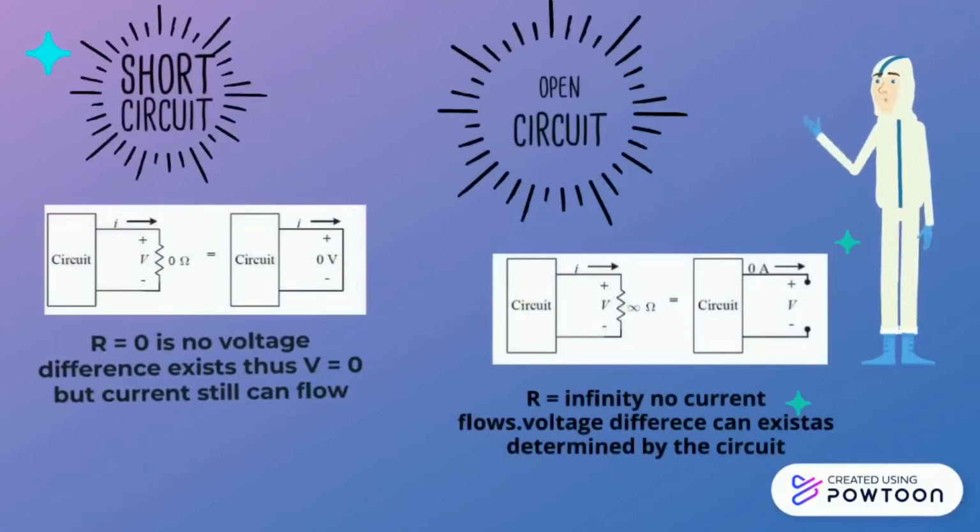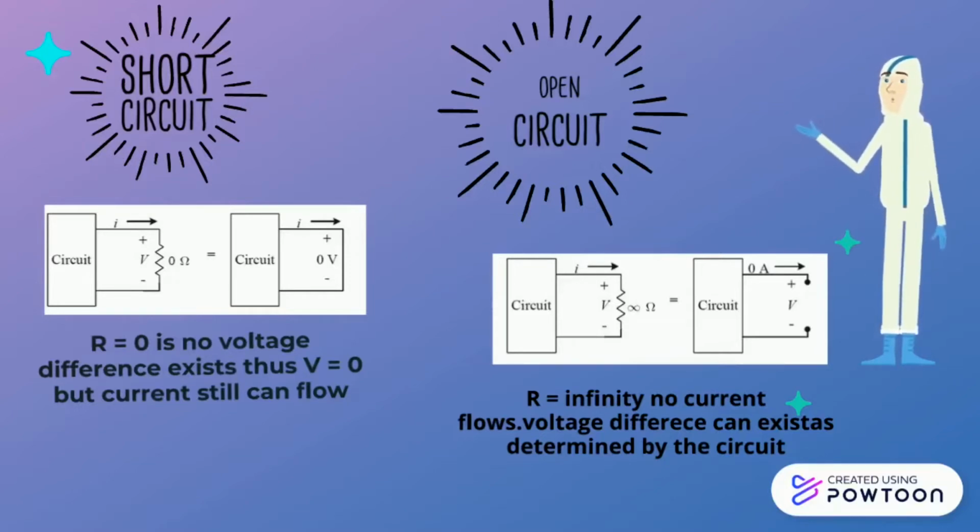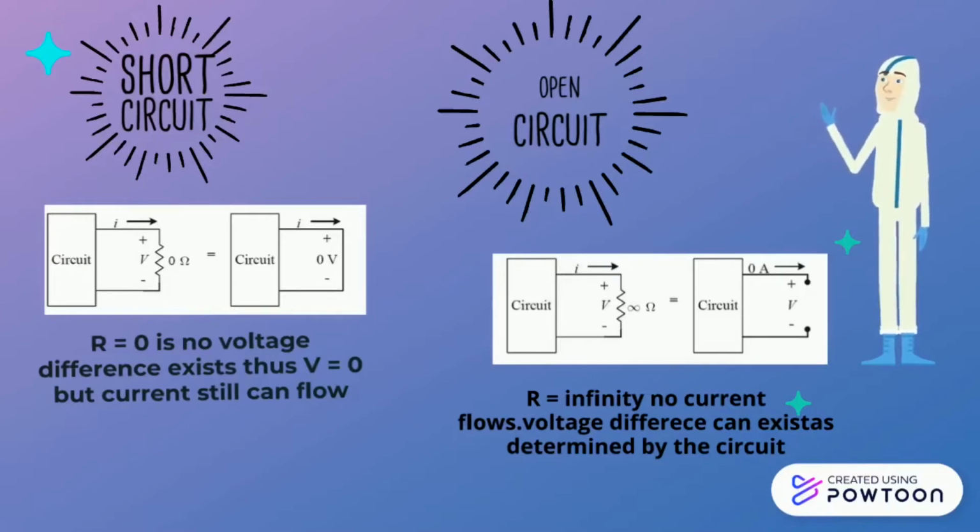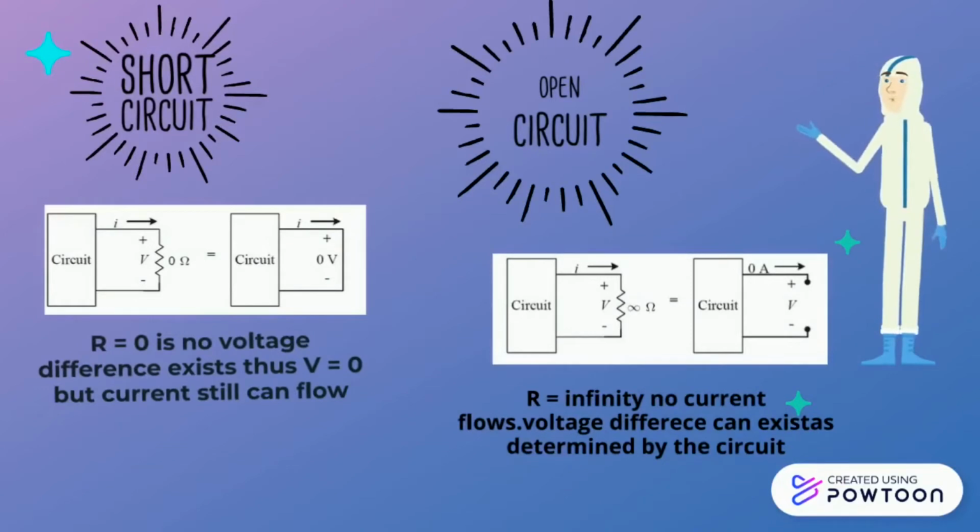In circuit analysis, a short circuit is defined as a connection between two nodes that forces them to be at the same voltage. In an ideal short circuit, this means there is no resistance and thus no voltage drop across the connection. In real circuits, the result is a connection with almost no resistance. In such a case, the current is limited only by the resistance of the rest of the circuit.